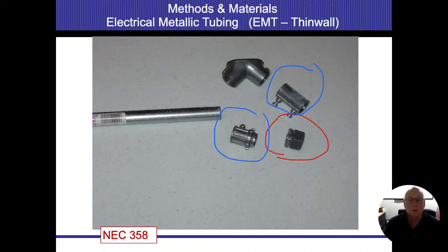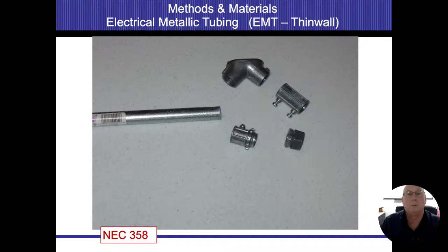For those that use thermal imagers inside the panels, I think it's a great idea. See which wires are hot. That could tell you if we're either overloading or too much bundling, or if we have loose connections. Just a nice simple thing we could do. Doesn't have to be 100% foolproof.